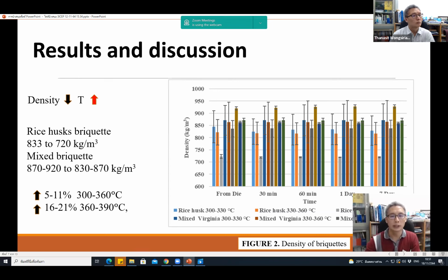Moisture was important when water-soluble compounds were present in the feed, such as starch and sugar. It also involves stability and expansion after compression of the briquette. Also, lignin binder was shown to help bridge the microgaps between the biomass particles. High pressure also generates high temperature in the die, melting the binding agent and increasing the briquette compaction and density.